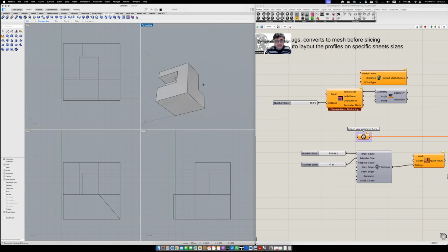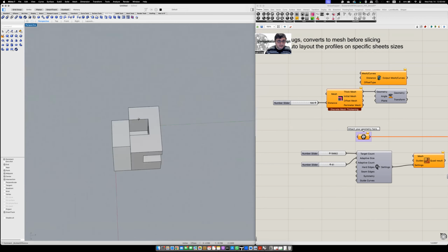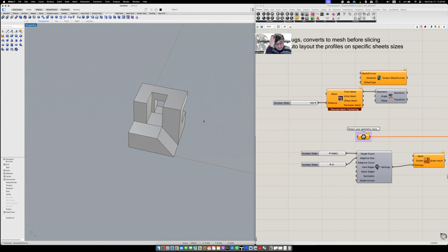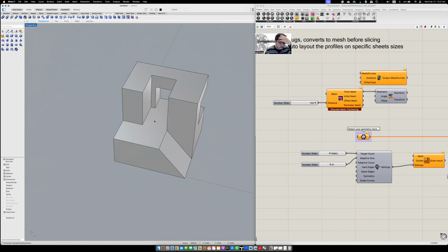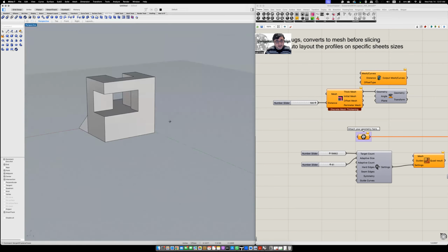So if you are a little bit adventurous, you can create other holes somewhere else, change the geometry. But let's say I'm happy with this geometry. So you see that there are some faces here that are divided. So let's take them out and tell them that they are going to be joined. So we call merge coplanar surfaces. Select object, and now we have a clean horizontal surface here. The lines disappeared. So it's called merge all coplanar surfaces. So we have this geometry.